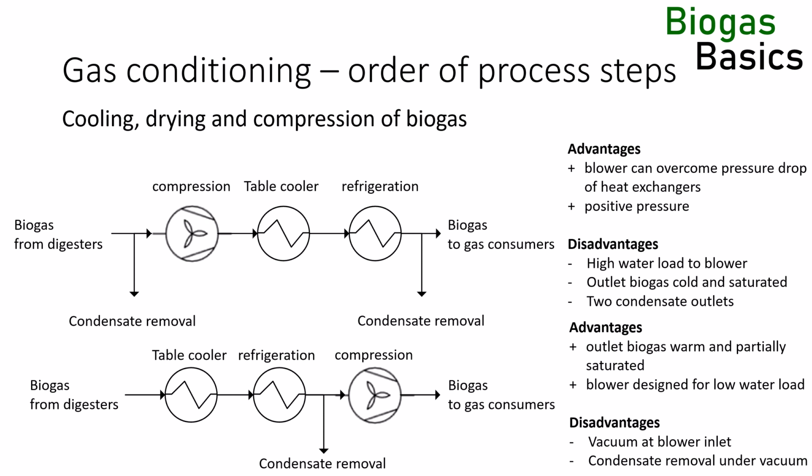In reality, this is very unlikely, though not impossible, as the volumetric ratio of air to biogas must be somewhere between 3.5 to 1 and 11 to 1 for a flammable mixture. So, there must be far more air than biogas for a flammable mixture. However, small local zones will form around a leak that contain just the right gas mixture for an explosion. Another disadvantage is that the condensate must be withdrawn under vacuum, which requires a local pump.